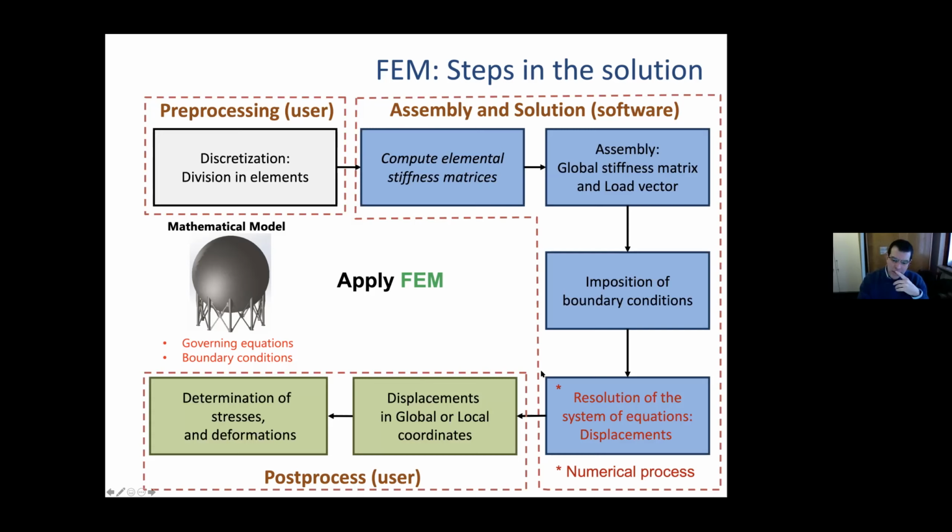Once the solution is available, we enter what is called the post-process step, which is basically displaying the displacements on our structure and calculating the stresses and deformation. That is basically what allows us to do all the analysis that we are looking for. It depends on what analysis you are performing. You may be interested in the stresses, in the strains, or maybe in combining the displacements, or any other output that can be computed from a finite element solution.